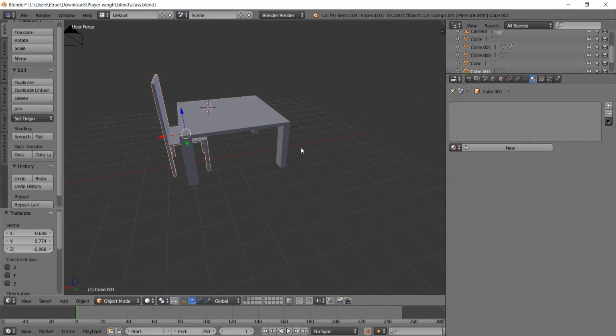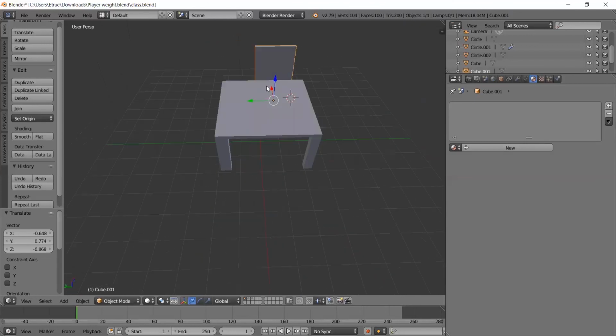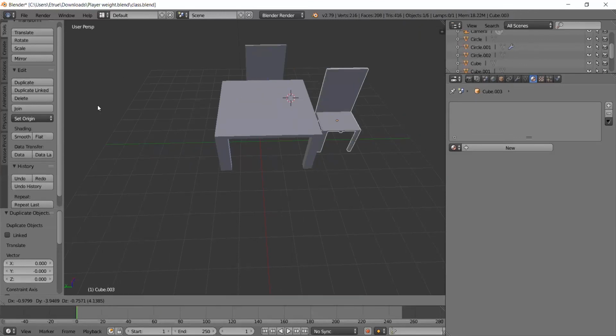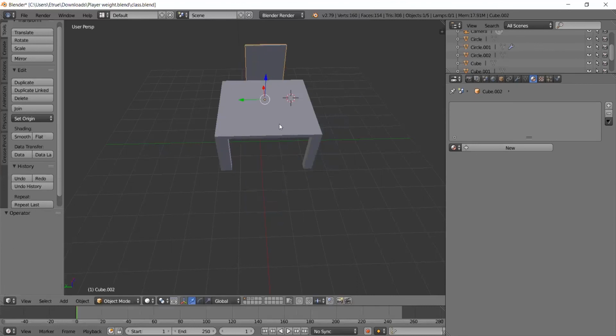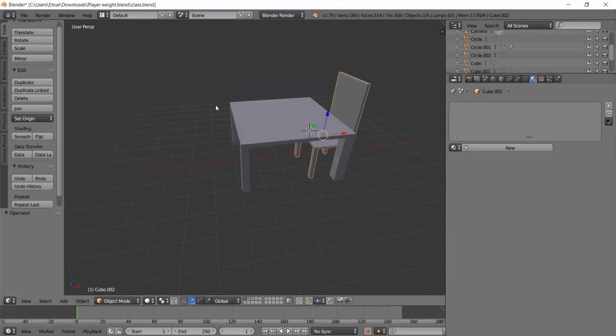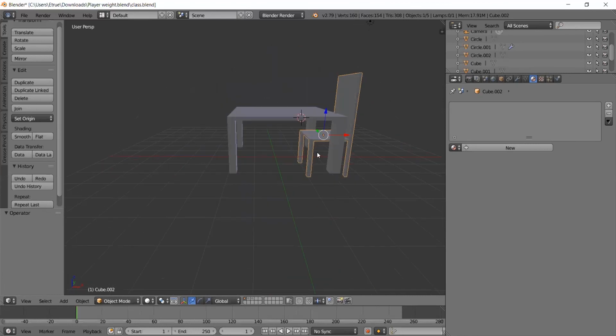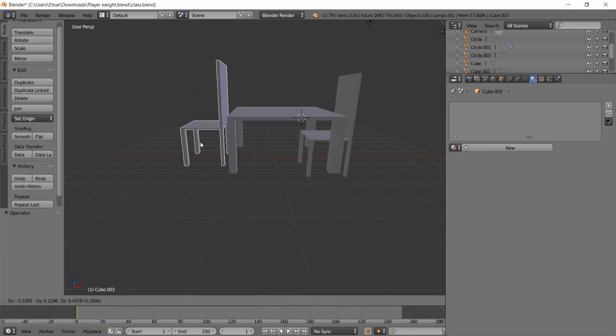Okay, let me push it here. So we are going to duplicate this chair, then position it here where you can see the mouse cursor. So Shift D, or you can also select. So right now the chair is selected. I'll come to where we have the duplicate, drag it to the position that I want. Okay, Control Z. Let me turn it a bit. Okay, so this way is okay for me. Then Shift D, position it here.